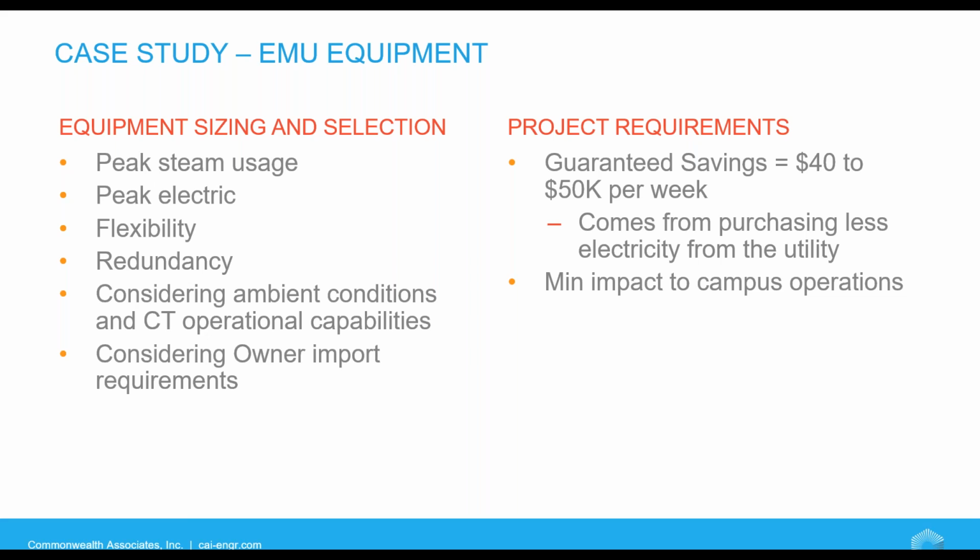So once we kind of knew what the configuration was, you took that information, put it into some thermal software, to model the plant with the various CTG makes and models, using the local ambient conditions to determine overall predicted performance, to also aid in determining the configuration and available redundancy.